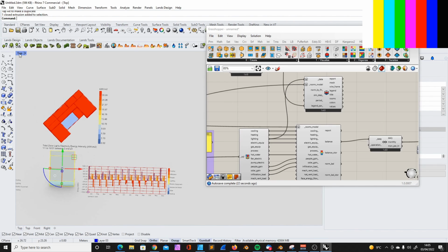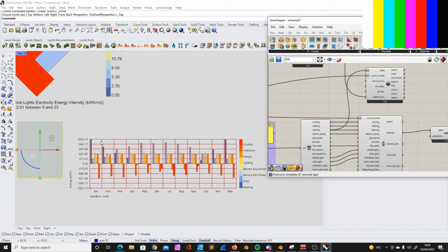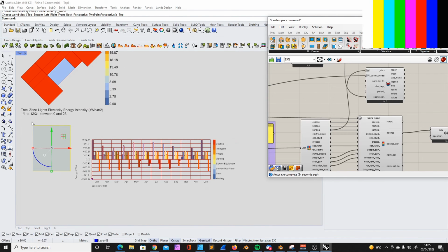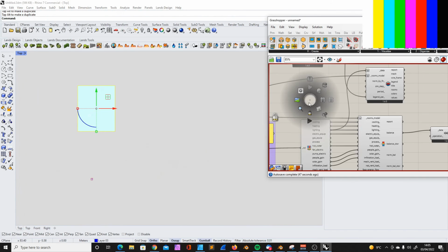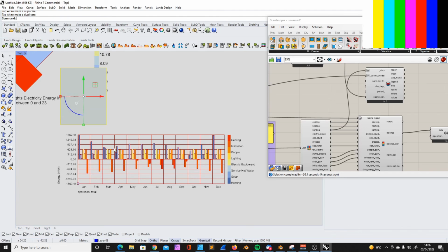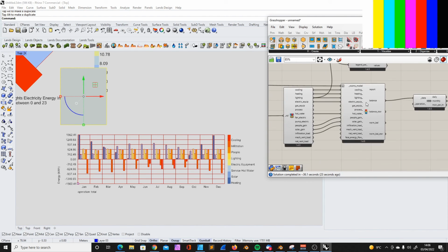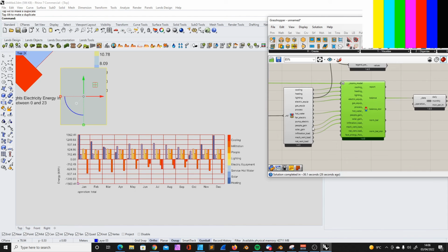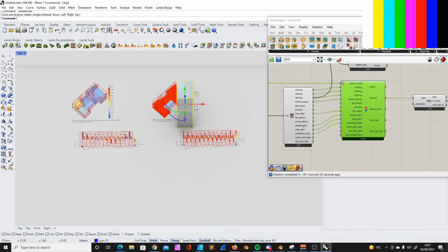Just to make sure that you see the difference, I'm gonna move this building around and let it run again, so you can see how this influences the output here. Maybe let's set it closer and let's see what it does. Yeah, you can see now this building has a huge influence on the solar gain here. It's much less now during the time where there's more sunlight. And yeah, that's how you can look at more of these data streams in the balance tool. Pretty cool. Okay, next time we try to wrap up